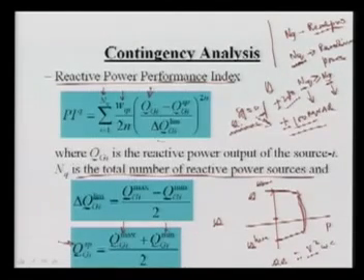Similarly, another term is the change in your reactive power limits, by which we are dividing. We are making this value significant because you can see how much margin you are having, what your range is here. If you are having less range, then this value will be more. It means you are operating that much closer to the limiting value. So this limit is basically giving an idea. For example, take two systems.